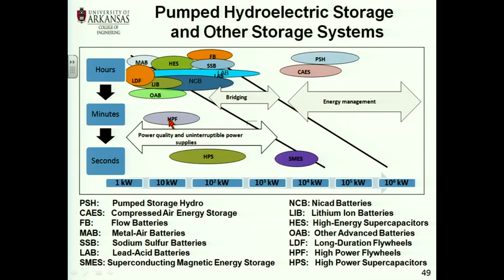Why? Because then you have to bring it up to a rated speed, right, to complete the cycle. You discharge, you charge it. You start, same with the ultracapacitor. You charge it, you discharge it. You charge it, you discharge it. So normally these flywheels or capacitors, they operate between rated speed or rated voltage and half of the speed.